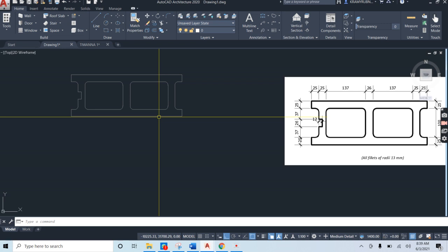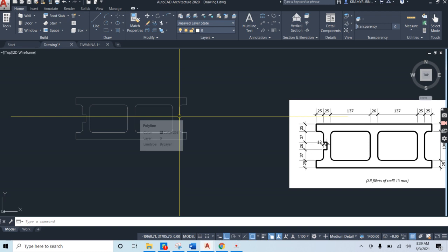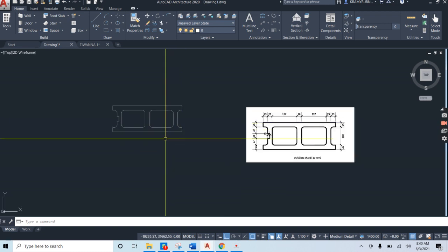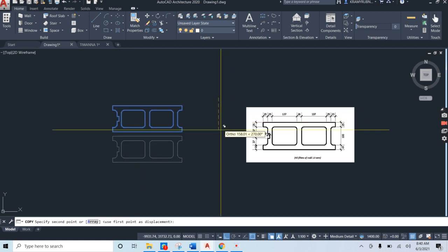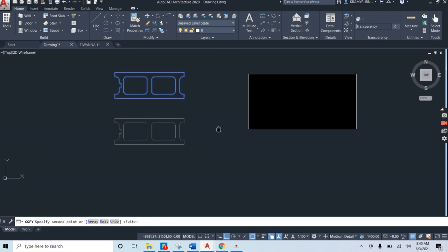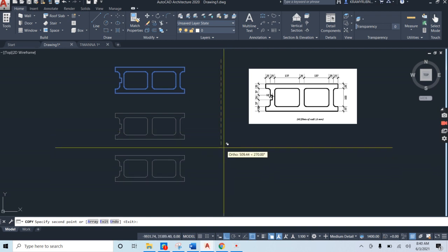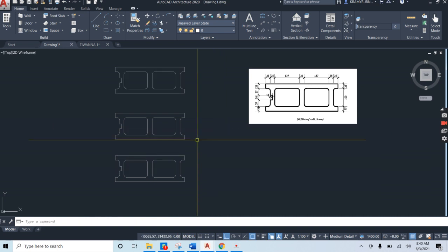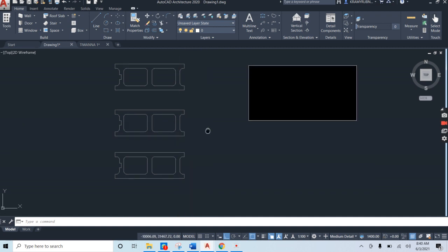Now, to be used in the production, in the construction of the wall, we're also going to be needing not just complete blocks, but also half blocks. Allow us to just make 2 copies. So let us select copy, select the entire block we wish to copy, and give 2 copies. Notice I'm ensuring that my ortho mode is on, thereby allowing my blocks to be copied in a straight line. It's important for what I want to achieve.